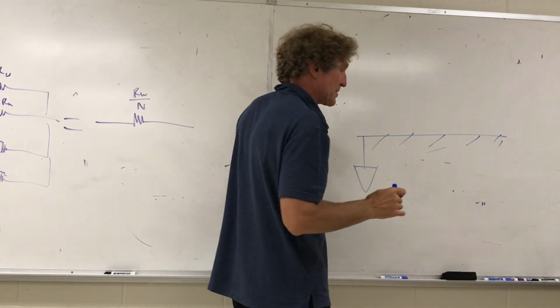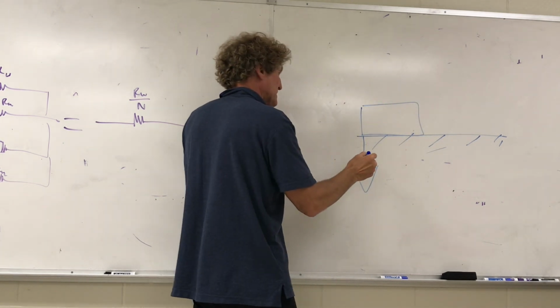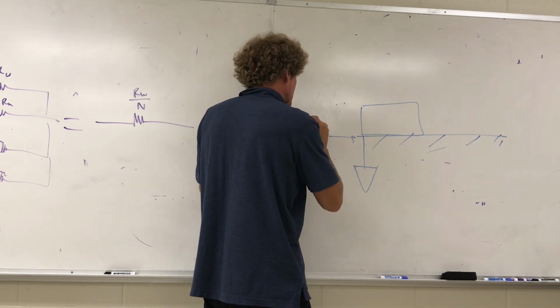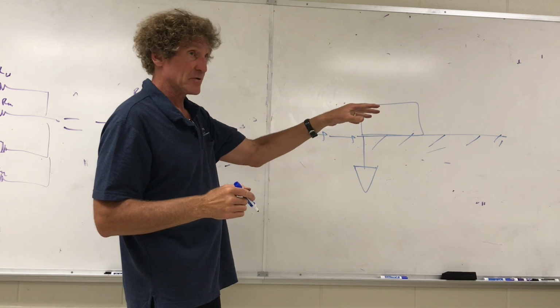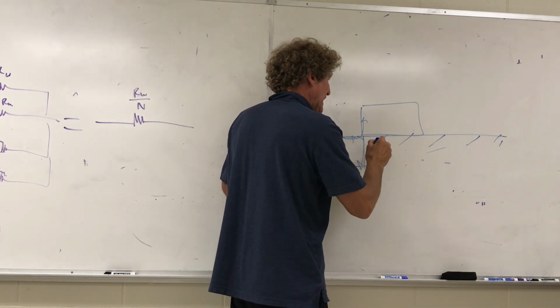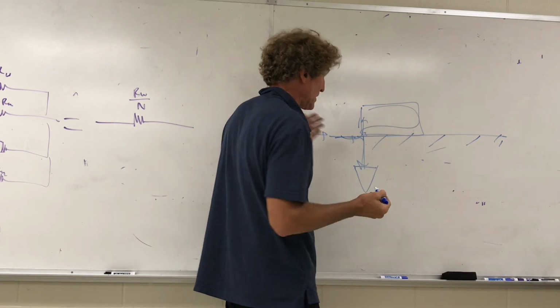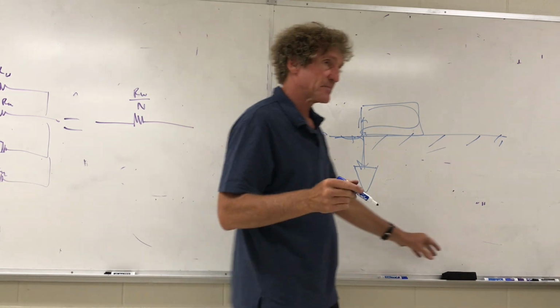All right, if you put a grounding rod there, and here's your house, and lightning hits, well, the current runs because of skin depth radially away from the actual lightning event. It will run this way, possibly. It'll try to run into the house, but if it can't get out, well, it's not really a problem. The house is secure. Here's the dangerous thing, especially in the South. I've seen this myself.